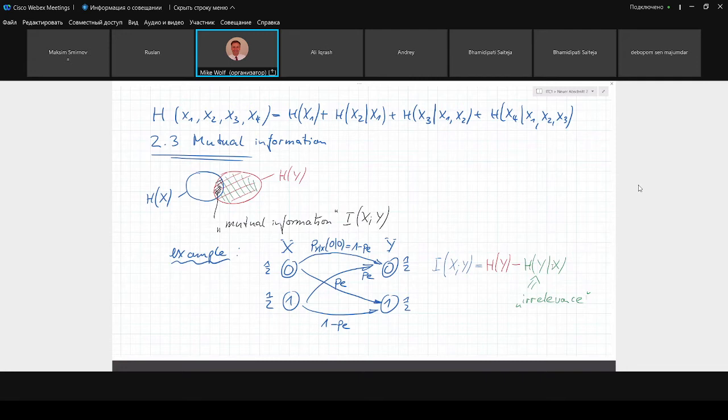And I have to take a look at y and say, oops, it's not 1, it's 0. So if there is a surprise in this y, if I know the transmitter has generated a 1, there should be, in an error-free channel, no surprise in this y if I know the x. This is exactly the meaning of this irrelevance. It's irrelevant information added by the channel itself.